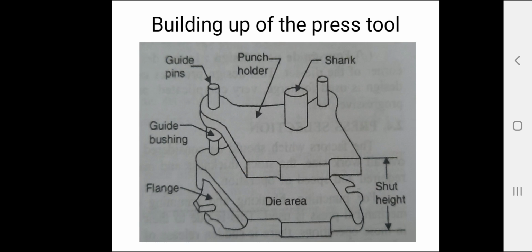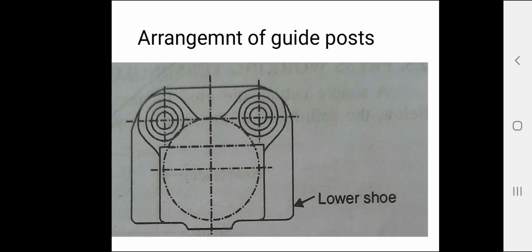So here it is a back post design. In this back post design, the die set has two guide posts positioned in the rear part. So this is the most frequently used design. This design gives a clear view of moving parts and there is no obstruction from guide posts. So this helps the operator when feeding from left to right. This design also leaves a clear space for hand feeding blanks for second operation.